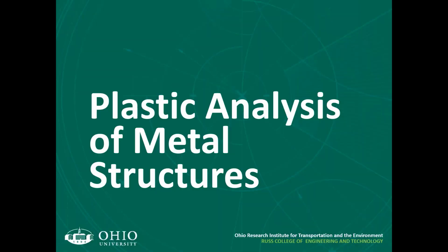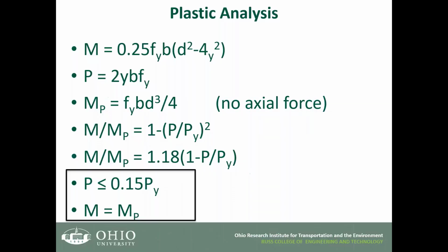Okay, so another principle I want to explain before I hand it to Kevin is that one of the things we use is a plastic hinge in the culvert to see how much capacity it has for the rating. To do that, I want to explain some basic things. I know all the engineers have a background in this and took this course as undergraduates in strength of materials, but they didn't go into that much detail on plasticity unless they took a course in plastic design. So let's go next.